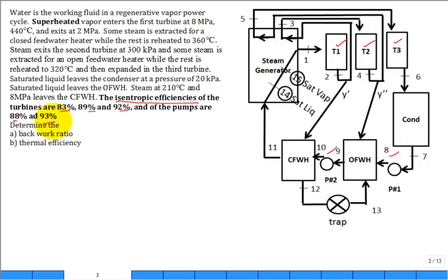Okay? If you know what you're doing, somebody says, can you please tell me the pressure at state 13? If I know the pressure at 4, and I know the pressure at 8, and I know the pressure at 9, or some combination, I can get 13, can I not? Somebody says, tell me the temperature at 8. That's a little tricky. It's going to be slightly above the temperature at 7. Now, to do it to 3 significant digits is going to be really, really hard.